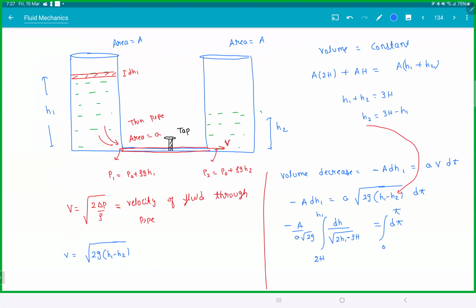You getting what we did? On both the sides, when the liquid is going, the pressure difference will keep changing. Because the pressure difference is changing, the velocity will change. And because of which the flow rate is changing. But इस बार दोनों साइड चेंज हो रहा है. One side is increasing and one side is decreasing. This question would be more deadly if I take this as A1 and A2. Same logic and concept, but mathematically it will become more complex with too many variables.